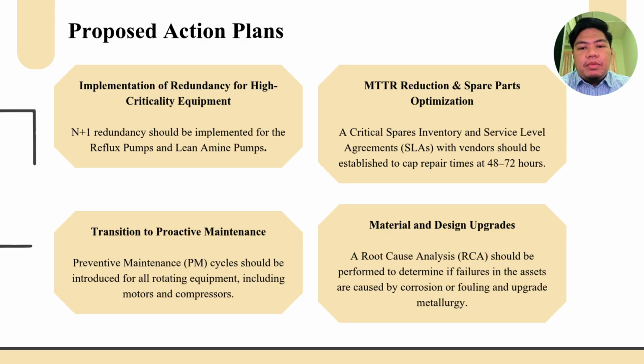Hi and Assalamualaikum. My name is Izu Afisha, and now I'm going to be presenting the proposed action plans. So we have four proposed action plans. The first one is the implementation of redundancy for high criticality assets. N+1 redundancy should be implemented for the reflux pumps and lean amine pumps. This is so that the system operations are maintained during repairs through the addition of a standby pump, which effectively masks the 6.549 kilo-hours of downtime observed in the current serial configuration.